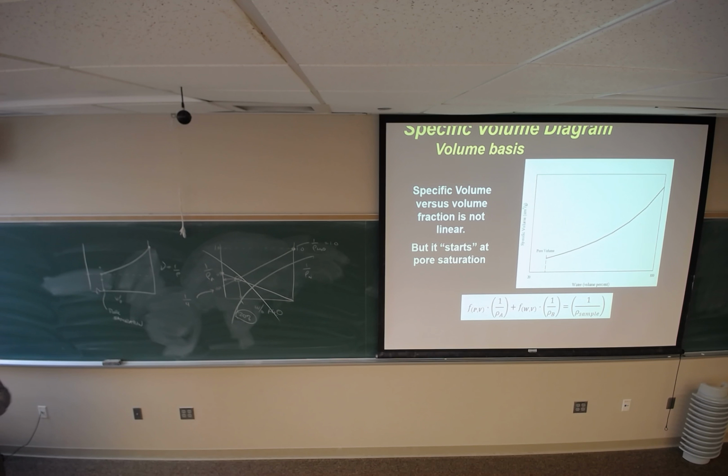Okay. What changes my pore volume? The density of the powder? No, we're talking about volume, right? We're talking about pore volume, not the density of the powder. How can I make my pore volume smaller? In other words, how can I pack my powders more efficiently? Different sizes, two different powders. Okay, like particle sizes, okay? If I disperse the particles, they will pack to a higher density compared to flocculated, okay? You should get that out of your sedimentation tubes, right?